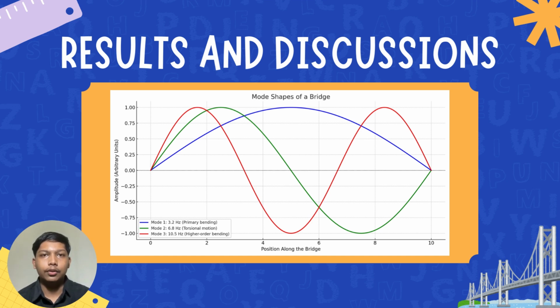Now, let's look at the visual representation. The graph shows the mode shapes along the bridge line. Mode 1, the blue line, has a simple single curve pattern indicating primary bending. Mode 2, the green line, has two peaks and valleys representing the twisting motion. Mode 3, the red one, has even more peaks and valleys showing more intricate deformation as the frequency increases. These mode shapes help us identify stress points where the bridge experiences the most deformation. This is critical for determining where reinforcement is needed.